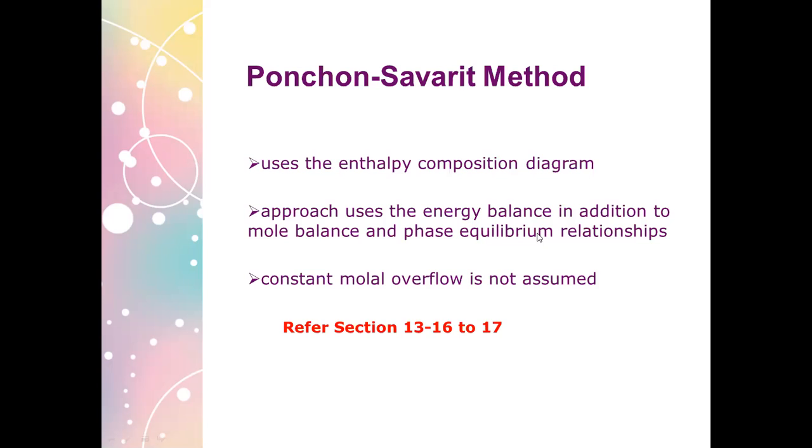Actually, the problem is accurately solved using this particular method. But McCabe-Thiele is close to the Ponchon-Savarit method, or arrives at values that are comparable to it. Now, there are two things. In Ponchon-Savarit you use an energy balance, and you are not assuming what we call constant molal overflow. This is the opposite of McCabe-Thiele, which we will be focusing on. McCabe-Thiele assumes that there is constant molal overflow.